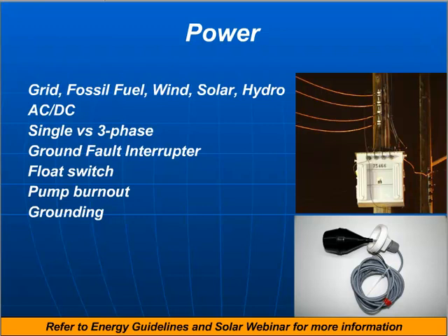You really need to understand who you are going to use, a local electrician or a local electrical engineer, to do that connection, and if so, what is their design, have you seen it, and is it appropriate? Or do you have somebody on your team who can put together that electrical design for the pump connection? Either way, it can be addressed, but it does need to be addressed. You need to understand: is it single phase versus three-phase electricity? What kind of grounding is it going to have? What kind of automatic switches is the pump going to have? What are the limitations so that your pump doesn't burn out? All those details need to either be accounted for in your design, or you need to have reviewed the design of somebody else so that you can ensure you're not going to have those kinds of problems.